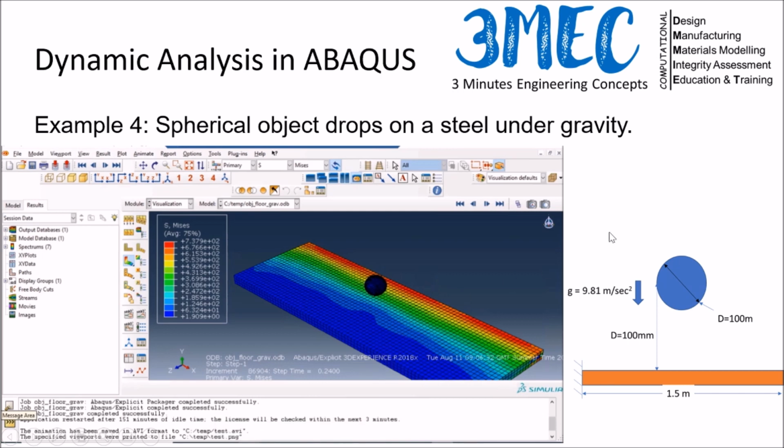Okay, so I hope this video helped you understand how to construct explicit dynamic analysis problems, how to set up the model, how to post-process the data, what assumptions you have to make, what inputs are required, what mistakes you can make as an analyst, and how Abaqus helps you rectify those in many cases. I deliberately made some mistakes, and you saw that Abaqus told us you need to define density, and you need to check the boundary conditions because your sheet is moving freely, for example. This kind of stuff.